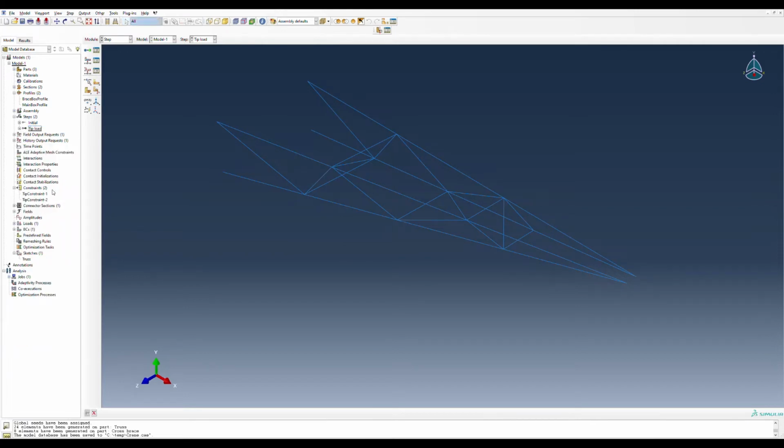And then the next thing that we had to do was to define our loads and boundary conditions. So for our loads, we're going to make sure it has a 10 kilonewton load going in the Y direction. So once you come over here, you have -10,000 going in the Y direction, as you can see over here. So we can go ahead and close that out.